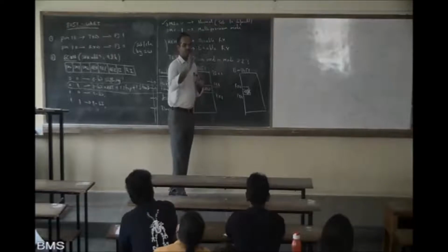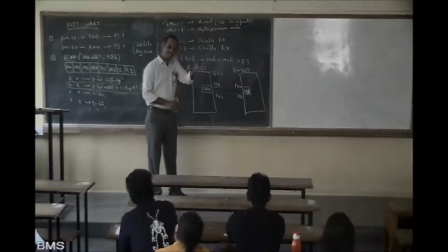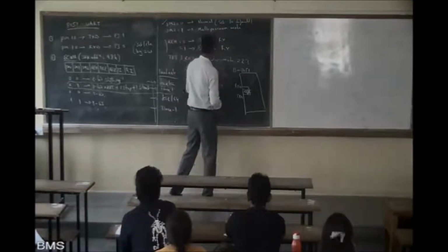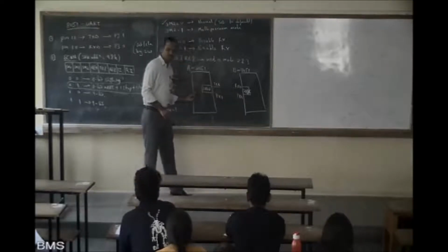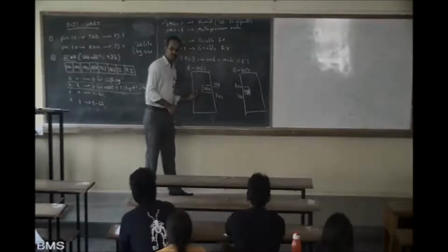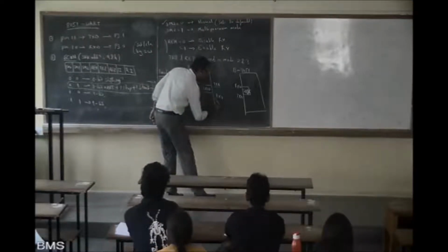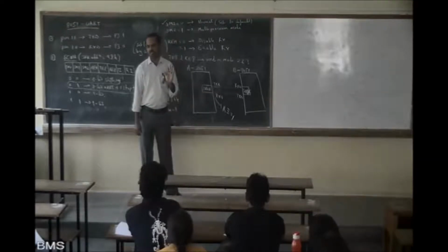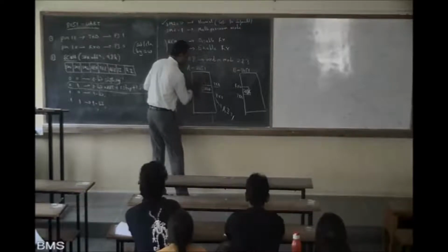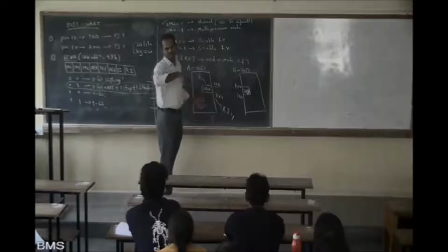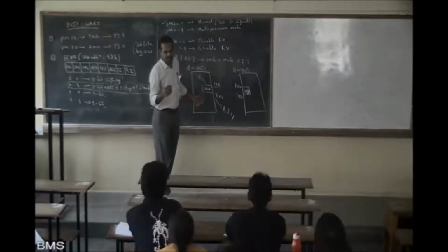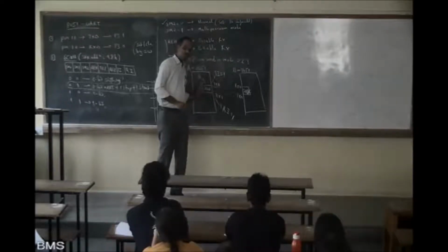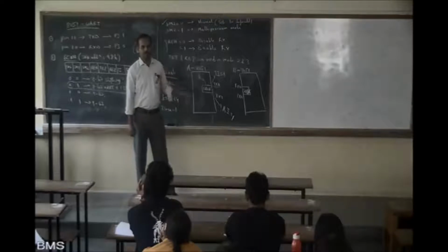So when TI is 1, what do you understand? Whatever I have put in SBUF has been transmitted, so I can put the next value. Is this clear? Similarly, when you are receiving, once all the bits are received into SBUF, the last bit, which is the stop bit, comes in, and then the RI flag is set by itself, indicating that reception is complete. So I can read this SBUF into A. You know how to read: MOV A, SBUF will transfer the SBUF value to A. So TI and RI flags: TI is set when transmission is complete, and RI when reception is complete. Is it clear?